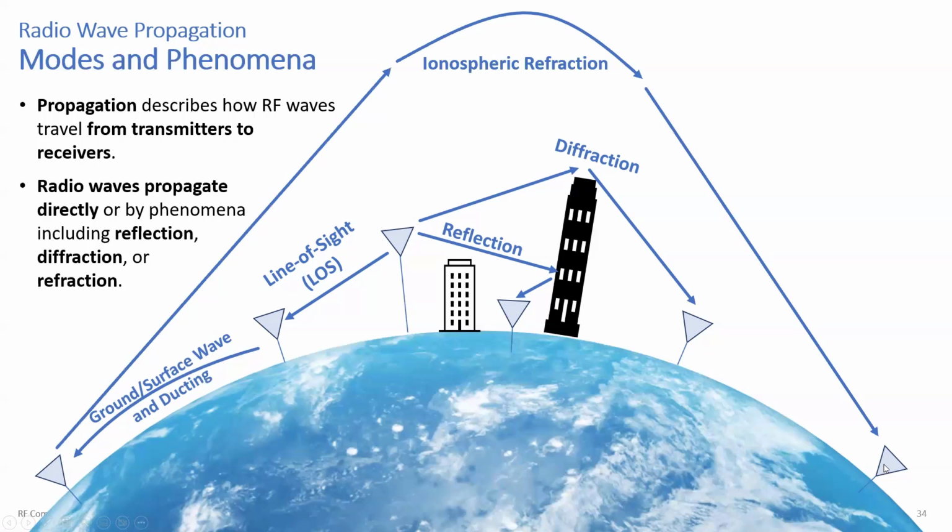Ionospheric propagation happens typically at what we call HF frequencies, ranging from a megahertz or 2 or 3 up to about 30 megahertz. They're effective depending on the condition of the ionosphere. If a signal is transmitted, it'll try to go out into space, traveling straight out. But because of the ionosphere, which changes at different times of the day, different times of the year, and depending on sunspot cycles, you get this refraction where the ionosphere bends the radio waves and they come back down to Earth.